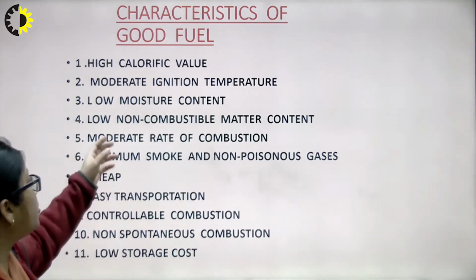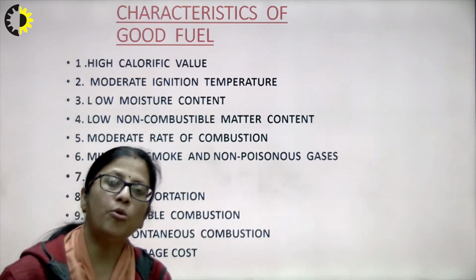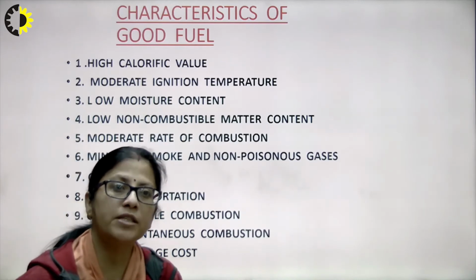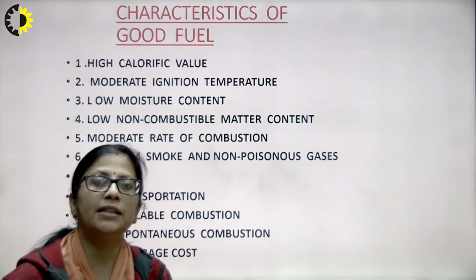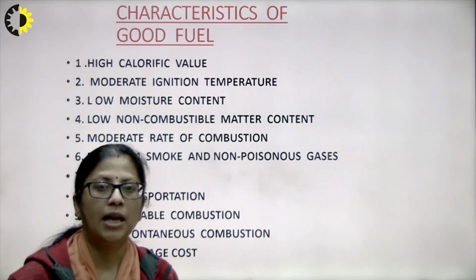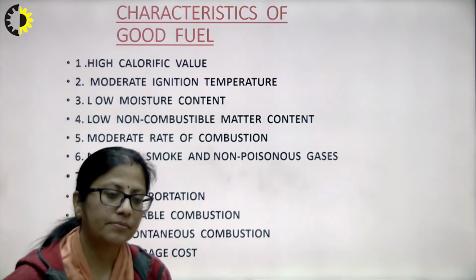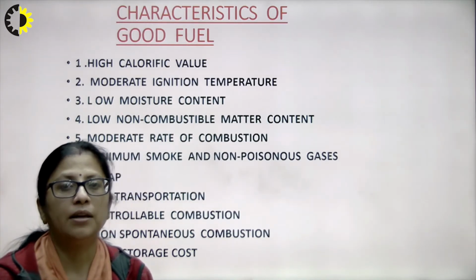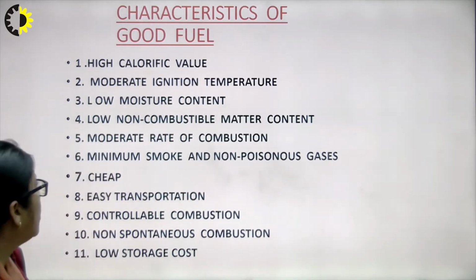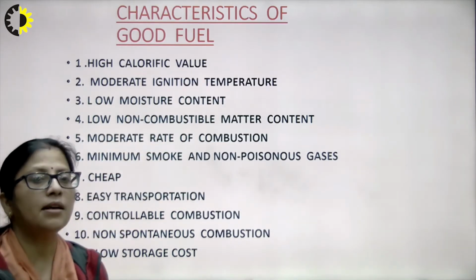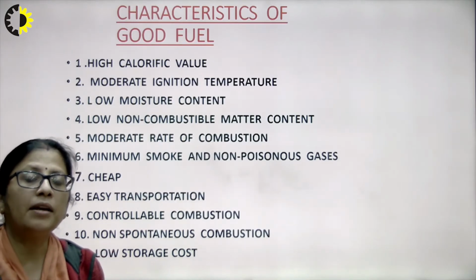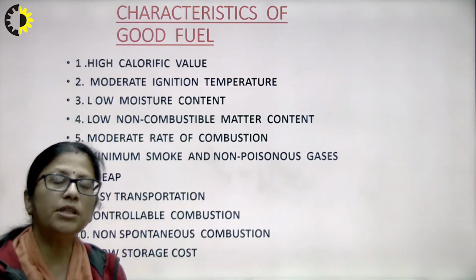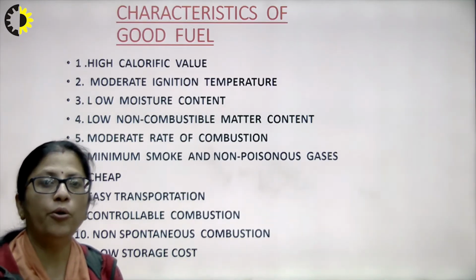Then next, it should have low moisture content, because if moisture is present in large quantities in the fuel, obviously it is going to affect the burning efficiency of the fuel. And in case of solid fuels, the matter which is left out after burning is going to be high. Next, low non-combustible matter content. If the non-combustible matter content is high, then it is going to affect the calorific value of the fuel. So this non-combustible matter content should be low in the fuel.